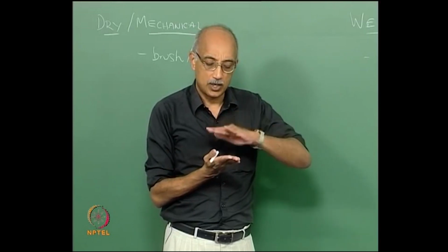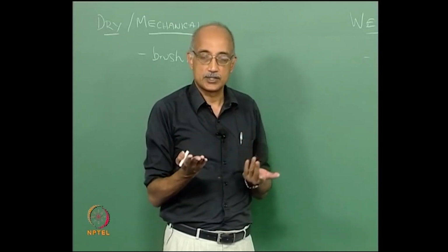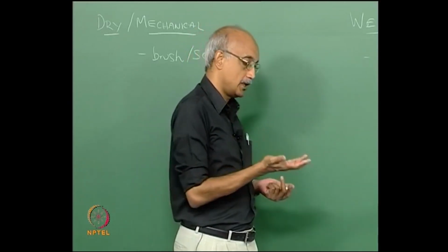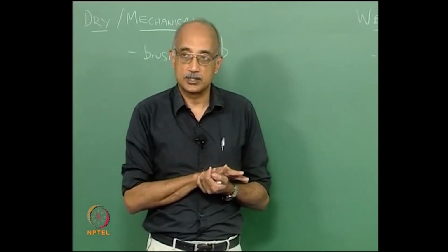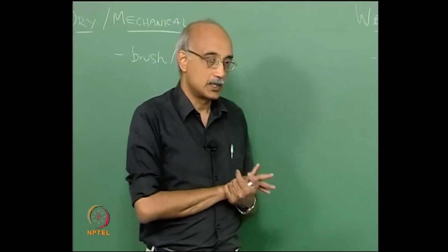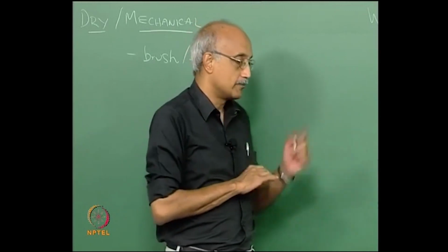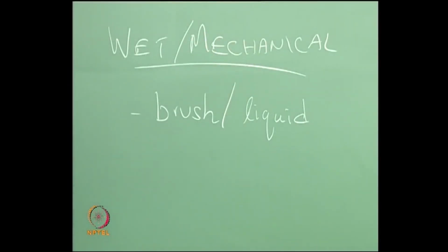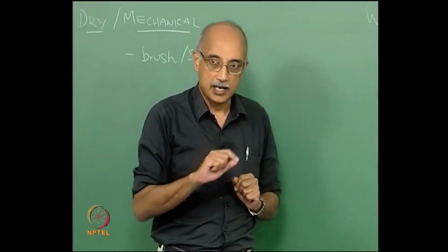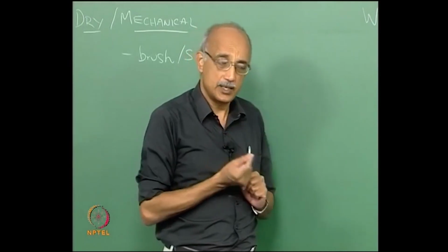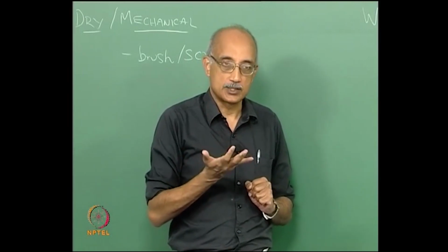So the solid brush tips stay essentially a few micrometers above the substrate surface that is being cleaned, and the liquid acts like a buffer and prevents actual physical contact between the particle and the surface, but at the same time it allows contact between the surface contaminants and the brush material. And so by taking advantage of this hydroplaning action, you can remove particles while at the same time not causing damage to the surface. And here again it is important that the liquid be able to wet the interface between the particle and the surface.